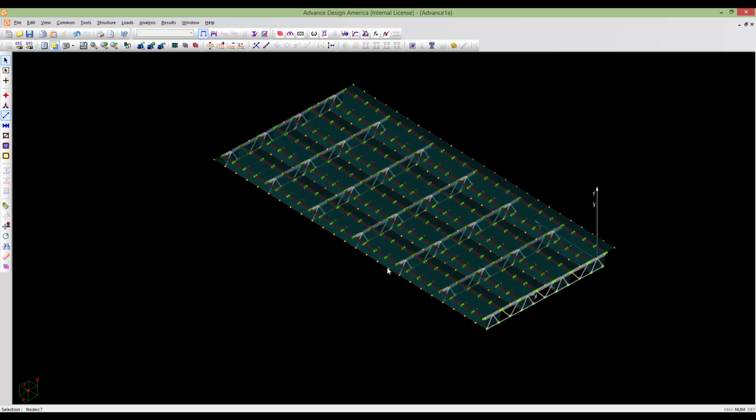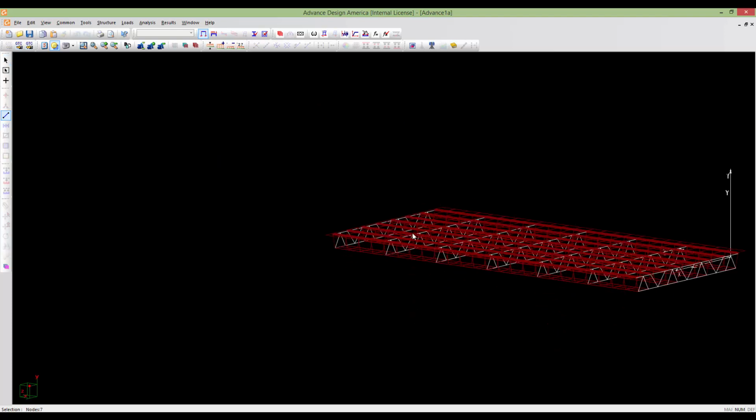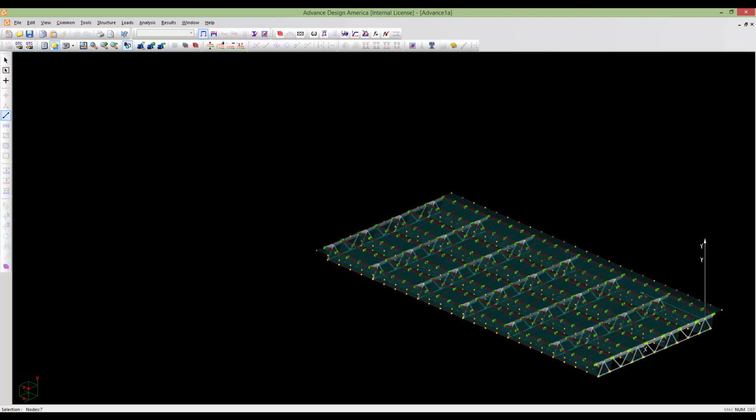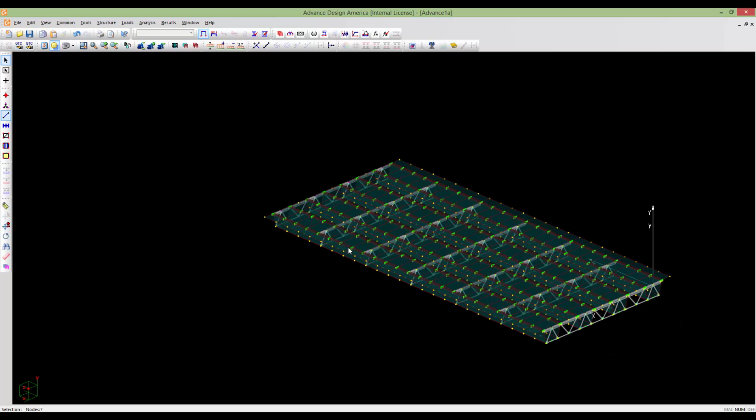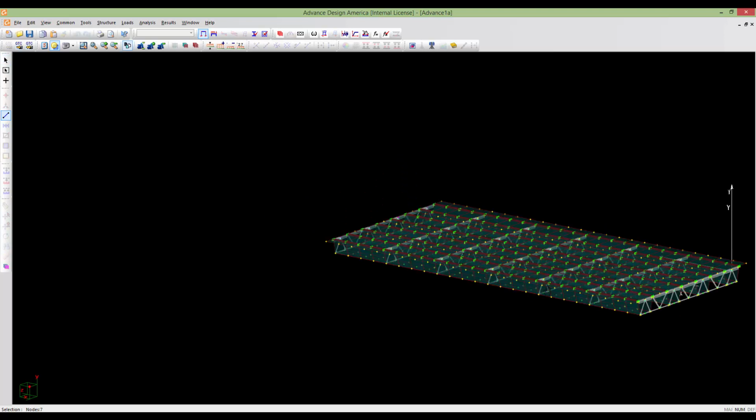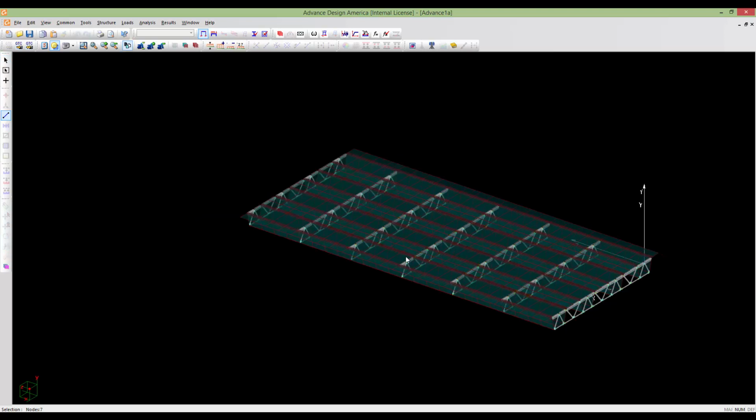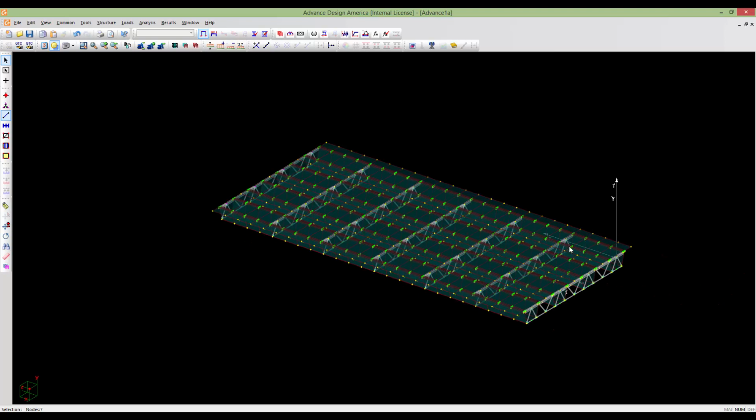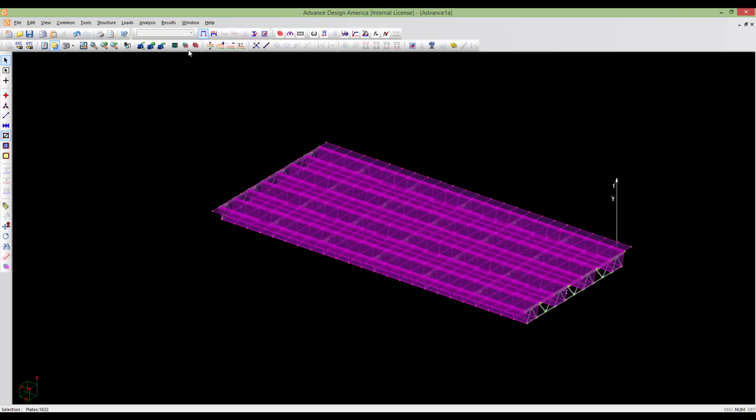In the next stage, I'm going to show you how to even define some extra L sections here to provide some lateral support for the girders. So to put those members easier, I'm going to hide these, which already defined. So select the plates, selection mode, mask them, OK.